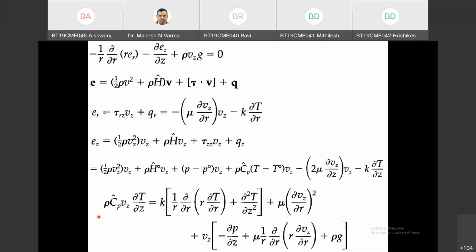Here roll number 47, Gurupreet. Why is velocity not a function of z? Due to the continuity equation, for a constant density system. Okay, it is not just the continuity equation; this is the continuity equation for a constant density system, del dot v equals 0, where you cannot have variation of z velocity with respect to z.